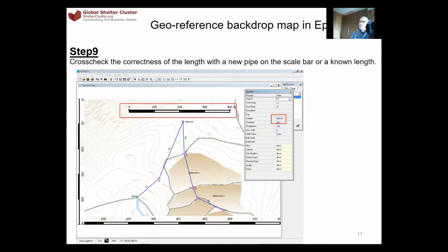So once it is properly inserted, you just have to put the junction, and the pipe's length will automatically be estimated, and you don't have to find the dimension of the pipe. The rest is like workshop 1 and 2. So you have to give the elevation, the water demand, the pump curve, and the pattern. And then you can run the analysis.